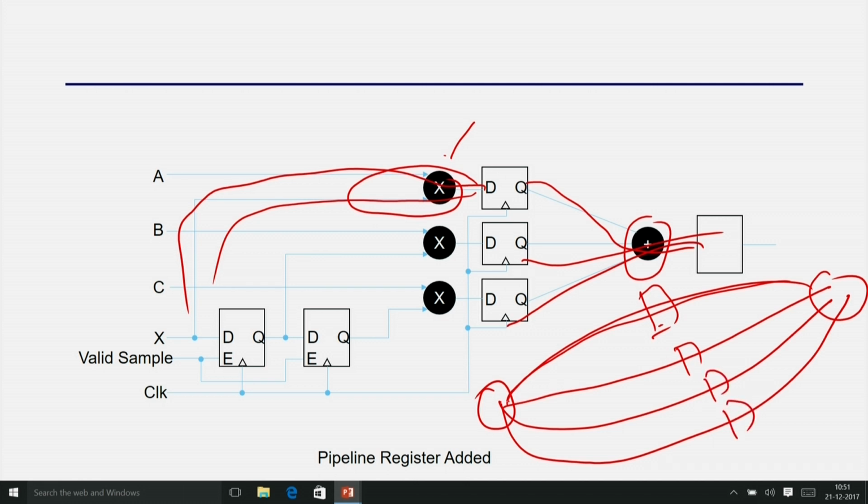Even if there are 4 multipliers in this path, and the other paths are simpler, with say only 1 multiplier, you cannot just say I have to add latency, so I will add it in between and I am done. That is wrong, because if you add 1 latency here, this data will be delayed by 1, but the other data will all come in earlier. Then the problem is that this is not synchronized.